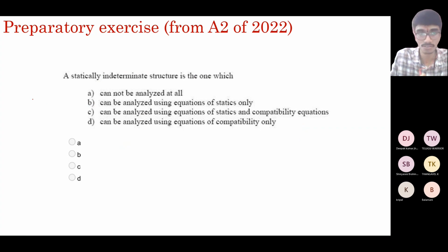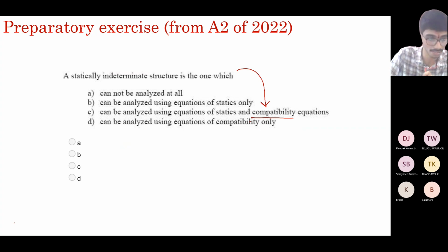So again, this is simple. What is a statically indeterminate structure? As I said, the equations of static equilibrium are not sufficient. You need additional conditions called the compatibility conditions. A statically indeterminate structure, by definition, is one which cannot be analyzed only by the equations of static equilibrium and also requires what are called compatibility equations. So that is a simple thing. We'll go to the next question.